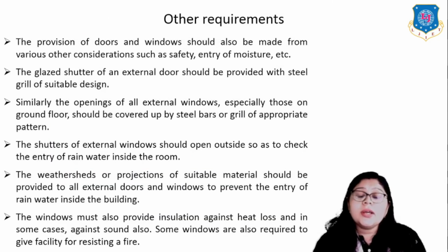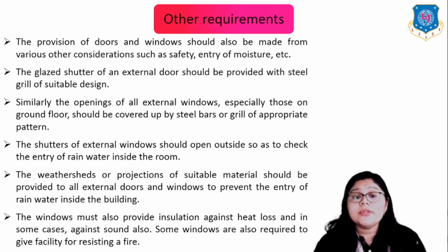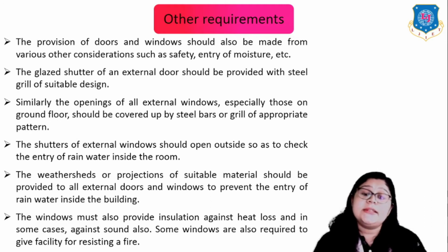For other requirements, we can say the provision of doors and windows should also be made from various other considerations such as safety and entry of moisture, right? The glazed shutter of an external door should be provided with a steel grill of suitable design.